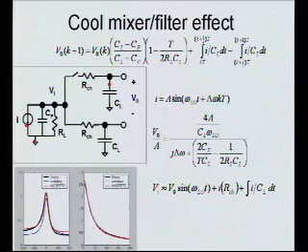If linearity was not a concern, what's the advantage of an active mixer over a passive mixer? Active mixers have gain. That's the basic benefit. So it's kind of a trade-off. When I was doing this design originally, I started out with an LNA and an active mixer because of that. And in the process I was in, I found that it actually made more sense to put all the power into the LNA and give it more gain, and then make the mixer passive, rather than doing two stages. But that's not always true. It really depends on your situation.